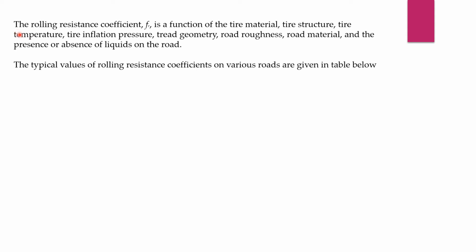The rolling resistance coefficient Fr is a function of the tire materials, tire structure, tire temperature, tire inflation pressure, tread geometry, road roughness, road material, and the presence or absence of liquids on the road. The typical values of rolling resistance coefficients on various roads are given in the table below.